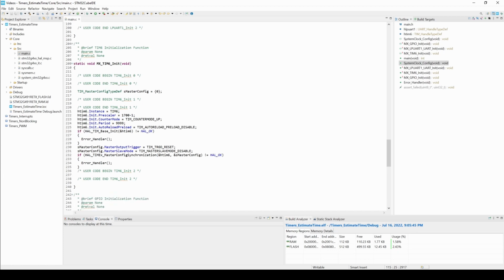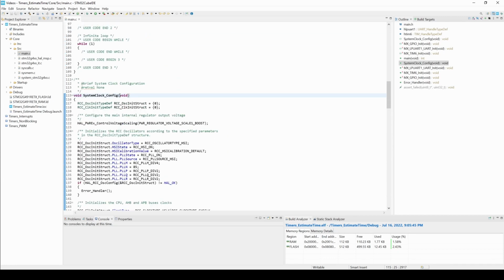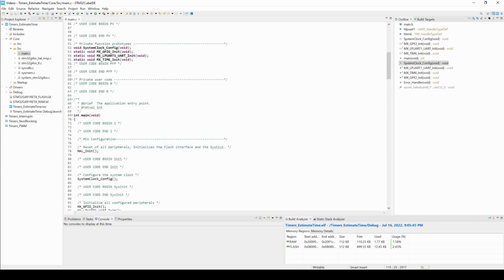Here, we can directly see that timer 6 is getting set up with all the parameters that we chose within the hardware configuration perspective. Notably, if your timers are ever not operating at the correct period or frequency, I would check the values in this initialization function first. Sometimes values don't get saved when you are changing perspectives or updating code. Anyways, for this tutorial on measuring execution time, we will begin in the user code private variables section.